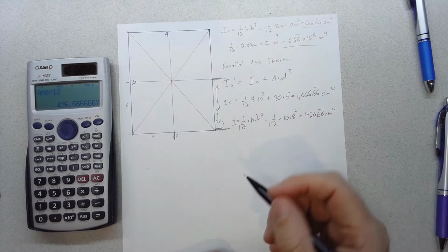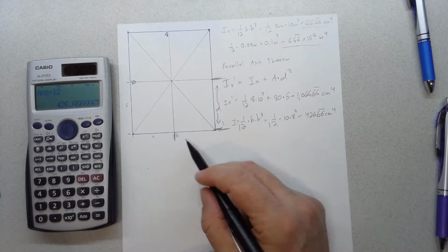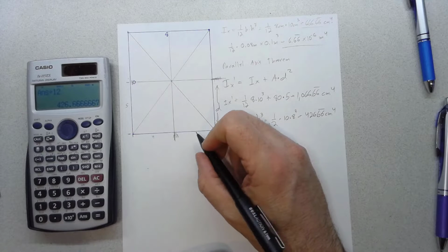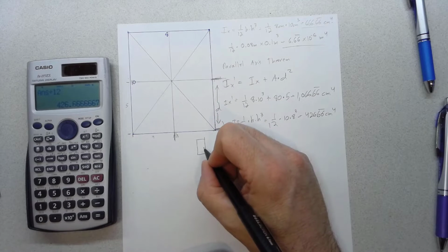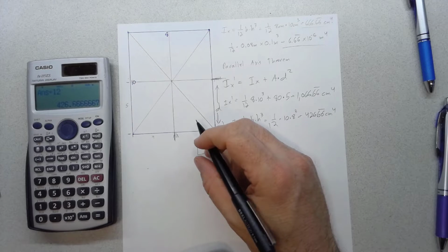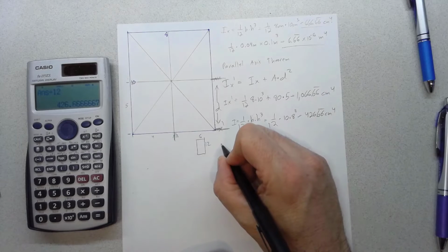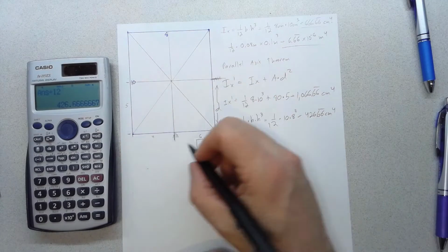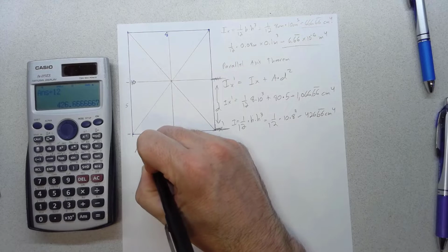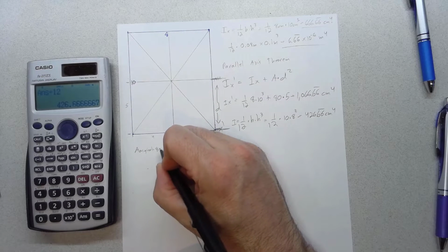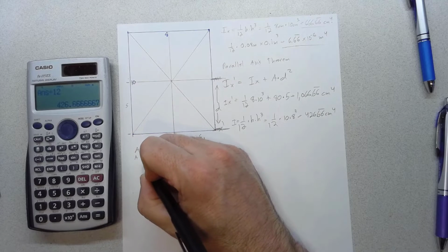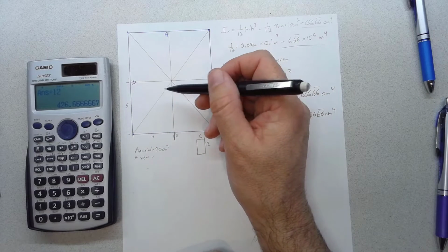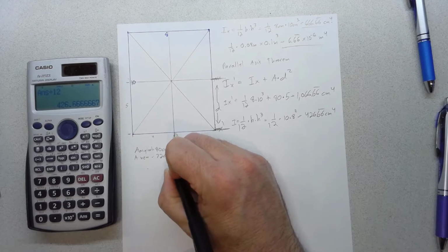Just to kind of demonstrate that, let's look at a beam. Let's say we took away 2 centimeters of width from this one and increased it in height so that now our beam was, I'm just going to draw it small this time. So we were 8 and 10. Now we're going to be 6 and 12. Let's look at the I for that. So total area, total material used for this one is 80. So area of the original equals 8 times 10 equals 80 centimeters squared. And the area for the new, I said take away 2 on that way, add 2. So we're looking at 6 times 12. That's 72 centimeters squared. So we're using less total material.